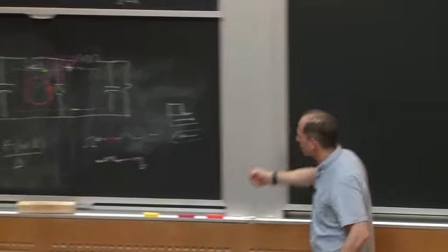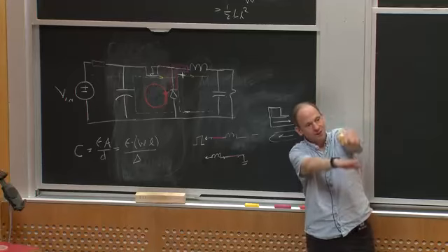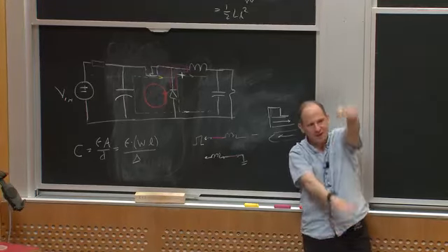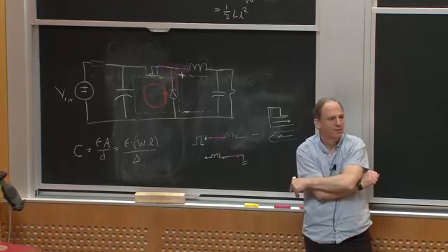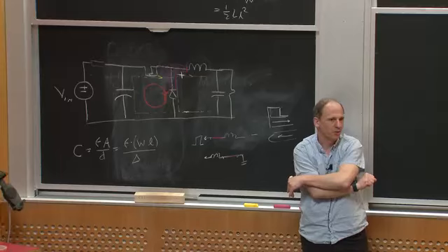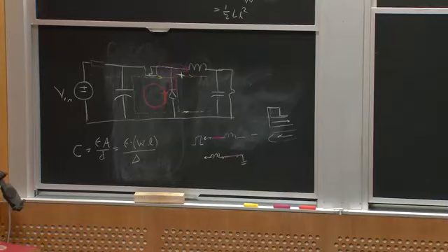But when I get down to the best interconnect strategy, at some point, if I put my trace and return close, I'm making the inductance low and the capacitance high, and vice versa. Okay? And you just have to think about which piece of trace it is and what it is doing for you. Any question about that?